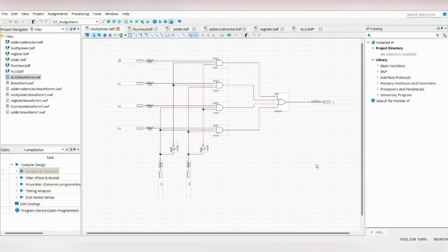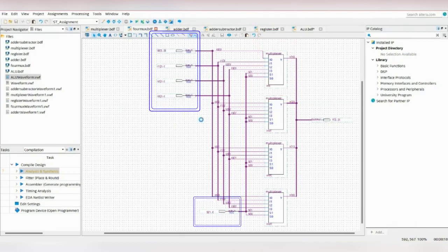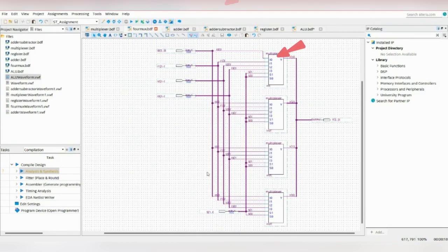To build a 4-bit 4-1 multiplexer, we need to insert the block symbol of the 1-bit 4-1 multiplexer that we made previously and connect it to the circuit, which has 5 inputs. We will connect I03 to I33 respectively and S0 to the first multiplexer. Continue the following steps with the change of the input to I02 to I32 and S1 to the last multiplexer.